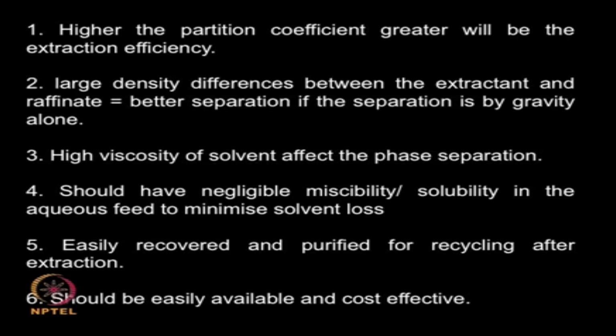Okay. So there are many other points which need to be considered when you are performing a liquid extraction. Higher the partition coefficient, greater will be the extraction efficiency. Here a very large number means extraction will be very good. Large density difference between the extractant and the raffinate, you can achieve good separation using gravity alone. That means after the mixing you can allow them to settle from each other, so there could be a separation, you will get a very nice phase separation because of gravity. But if the density difference is smaller, then you may have to resort to some sort of a centrifugal separation.